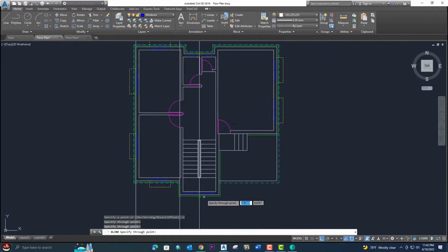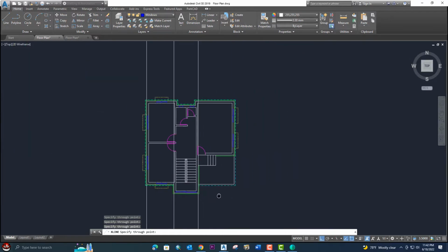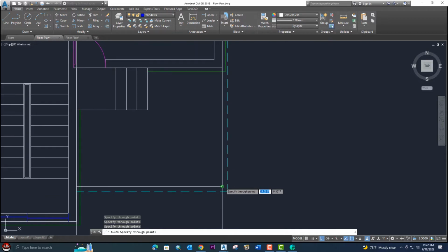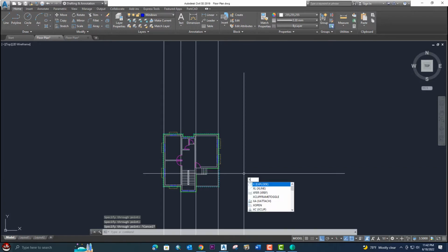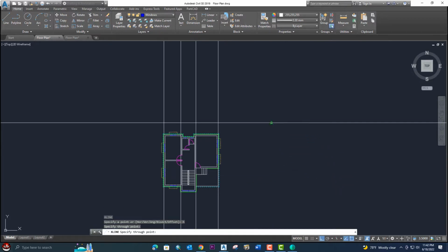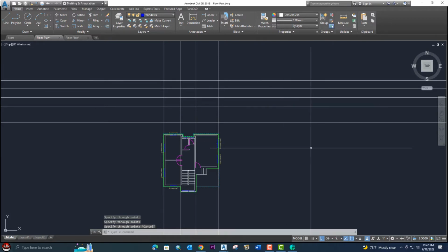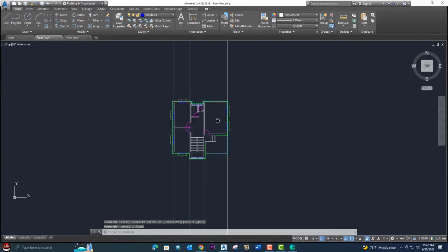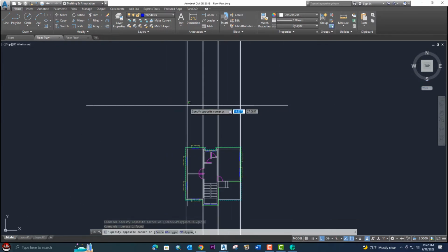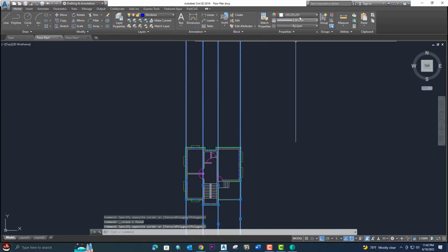So now we will take these external walls. We don't need to take internal walls. Take the external walls first of all. Okay, and also we need to change the colors. Later we will change the colors. We will just select also the plinth projections. Okay, so XL and enter H. H is horizontal, and you can easily draw the horizontal projection with the help of the shortcut key.